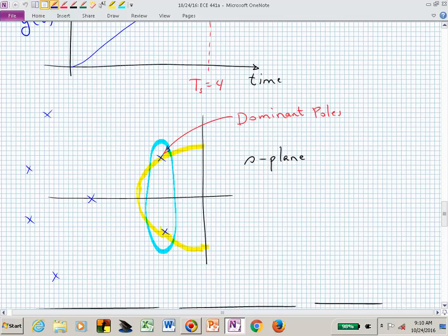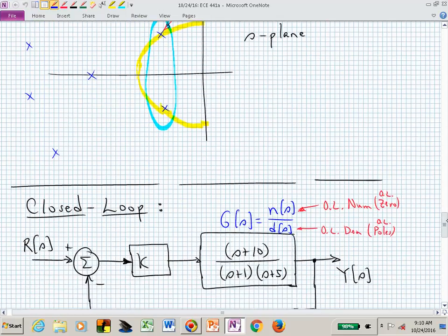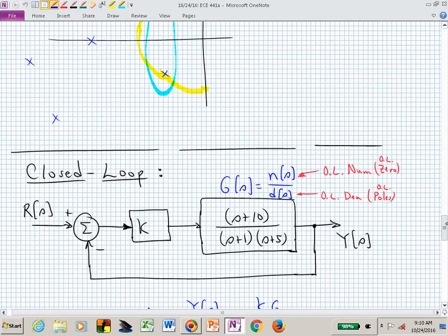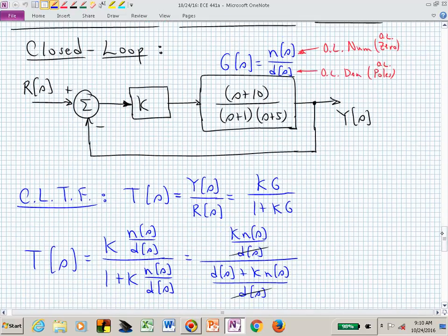On exam 3, we may have 7, 8 poles. Who knows how many poles we get. But what we want to do is change that. Obviously, if we wanted a 1-second settling time, and this was our system, we now need to change that. One way we can do that is to close the loop, introduce feedback, where we're simply measuring the output, feeding that back, and comparing that to the reference input, scaling that by a gain K, and that gain K is really what we can adjust.